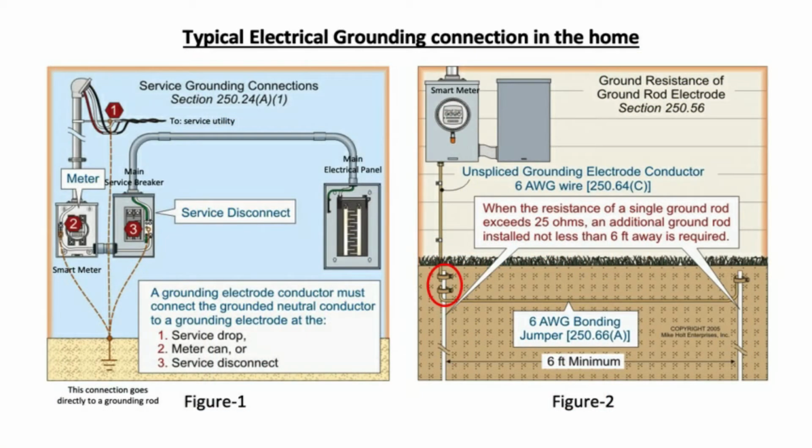Now this next image shows what happens if you do have a ground rod connection, say, for example, your cold water pipe is buried in the earth but not running through the earth up to 10 feet, or maybe it's made of plastic, like I talked about before. You can't ground a plastic water pipe, so you wouldn't be able to use your cold water pipe directly as the grounding electrode. You need a supplemental connection here, like a ground rod, for example. So that's another means of doing this.